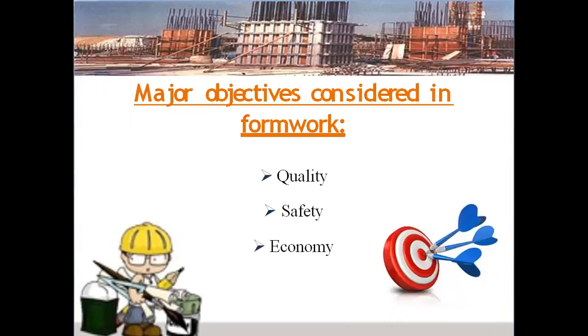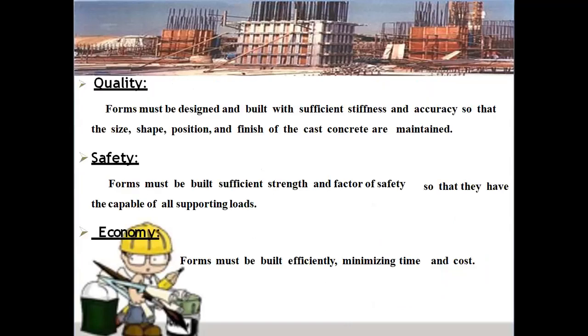So the major objectives considered in the formwork are quality, safety, and economy. Considering the quality of the formwork, the forms must be designed and built with sufficient stiffness and accuracy, so that the size, shape, position, and finish of the cast concrete are maintained.